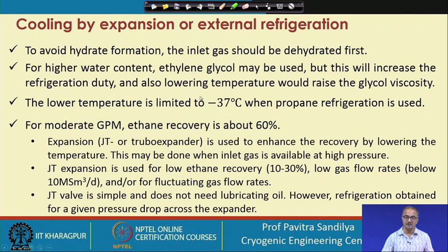And one more thing: if we now lower the temperature, what will happen? It will increase the glycol viscosity, and if the viscosity increases, it means more resistance to the flow of the gas streams, and in that way our pumping power will also increase. But we have to understand that in many of these things, if they have to be done, they need to be done and we cannot avoid it, and we have to accept some kind of penalty in exploring these various options.